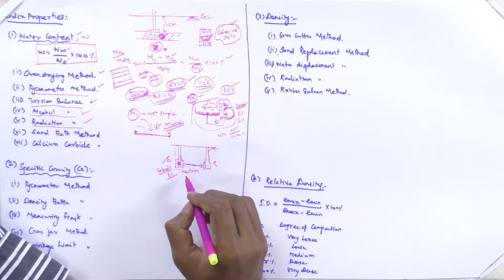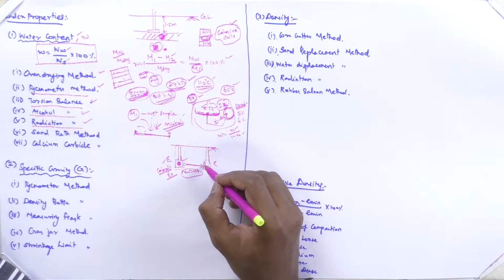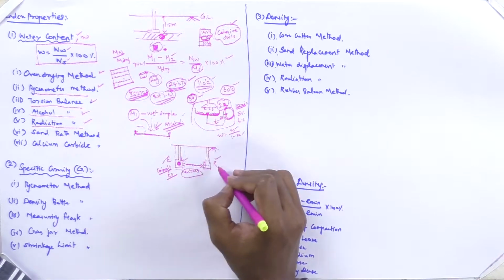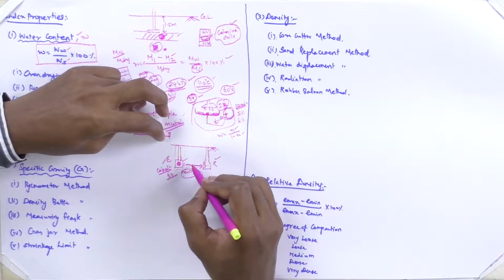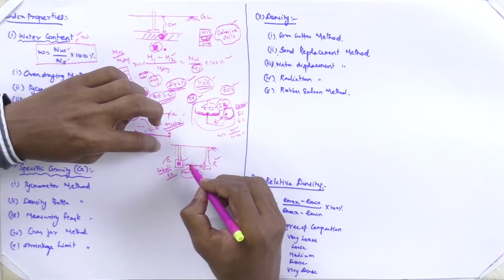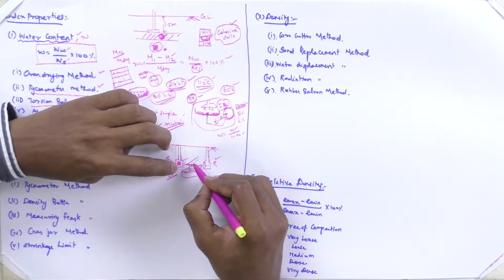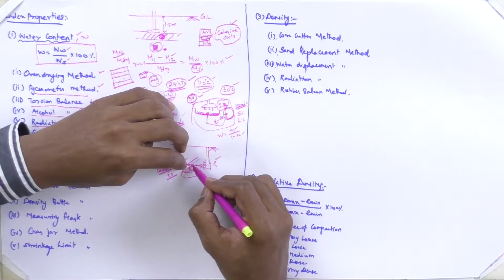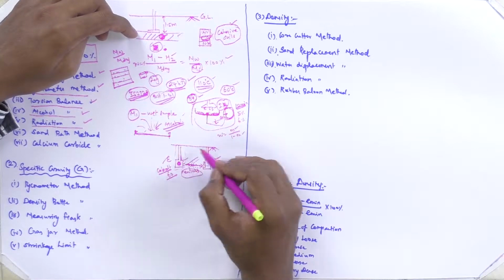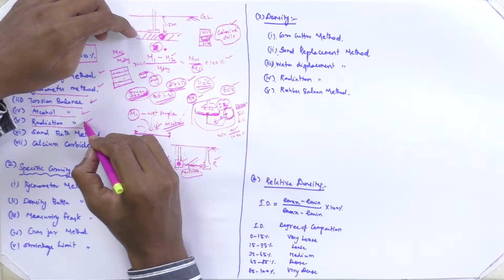So this receiver will receive the neutrons. The density or concentration of neutrons released by the emitter is measurable, and the density of neutrons received by the receiver is also measurable. While comparing these two densities or concentrations of neutrons, we can compute the moisture content present. How? The moisture present in the pores scatters the neutrons. These molecules can scatter the neutrons, so only a lesser density of neutrons will reach this receiver. This difference can indicate the moisture present. So that is the radiation method.